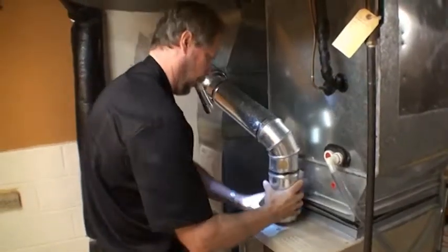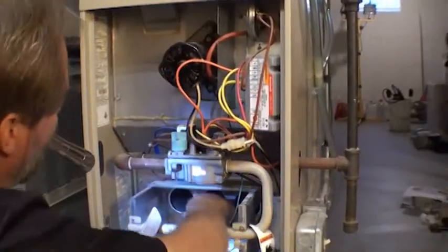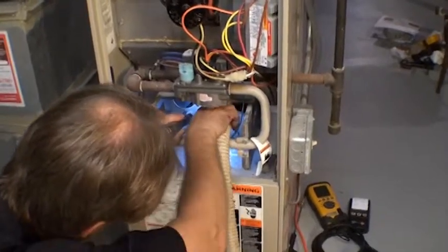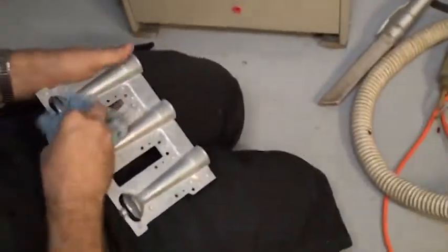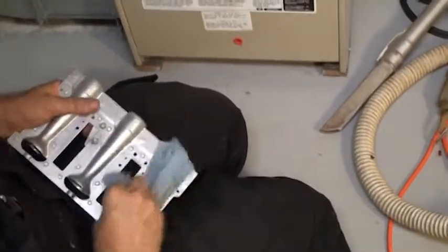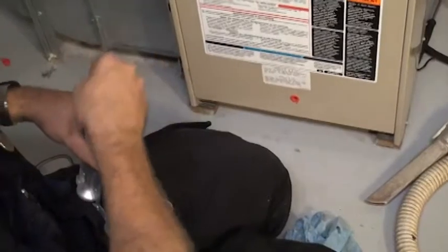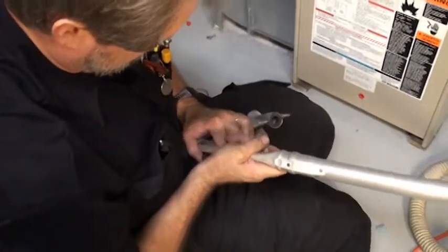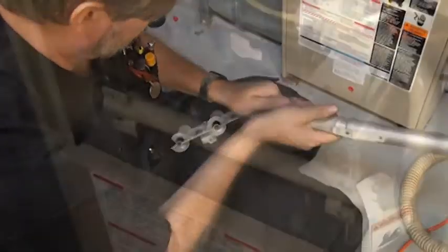Reattach the furnace flue securely to the chimney and furnace. Brush and vacuum each chamber of the heat exchanger. Cleaning the burners varies by each burner type. The power burners shown here need to be removed and brushed thoroughly, including each burner, port, and crossover. Steel burners will need to be filed and brushed. Before reinstallation, all burners must be thoroughly vacuumed.